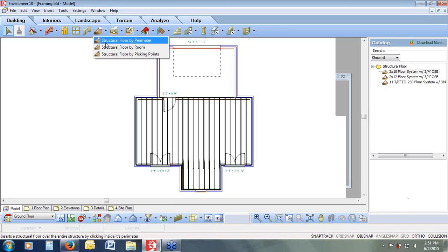Once they're in, we can cycle select to select that system. So I'm selecting the wall, but then holding down my shift key and moving my scroll wheel on my mouse to cycle through all of the elements that have an endpoint, a line along that same line.